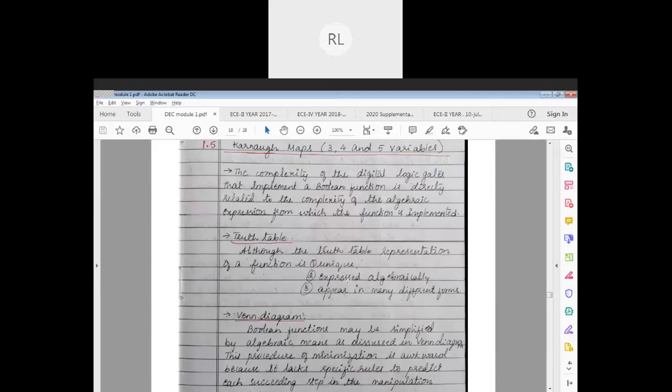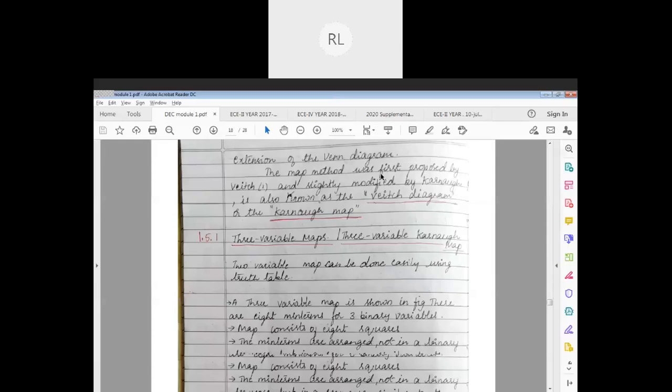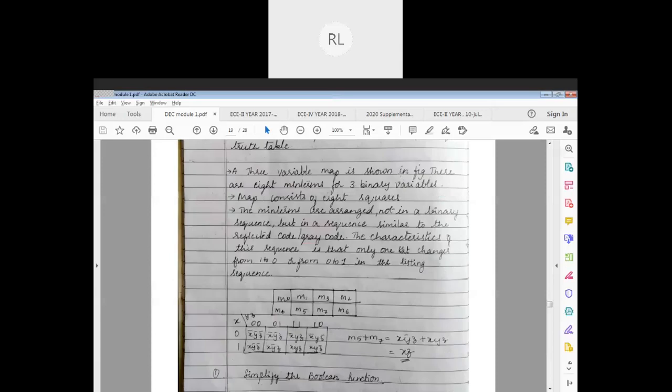See, for example, we had 3 bits here, x, y, z. Using just 3 bits, it took us a little extra effort in taking those common terms, repeating them, and trying to understand how to group them and reduce to our final format. Similarly, as we increase the number of bits from 3 to 4, 5, the complexity also increases. So that is made simple for us using KMap or Karnaugh map.